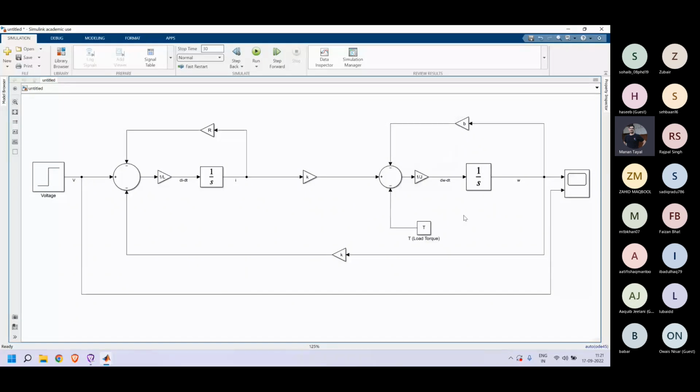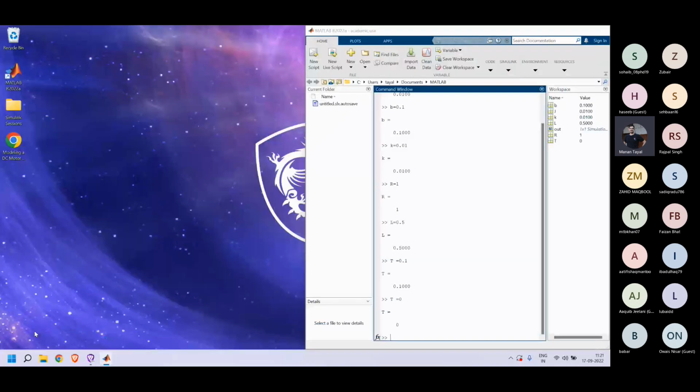So this external torque may be due to some external factors, trying to make the motor rotate in some other direction. It accounts for an external load in a different direction from my voltage. If I change my external torque to 0.1, I'll have to increase the voltage.